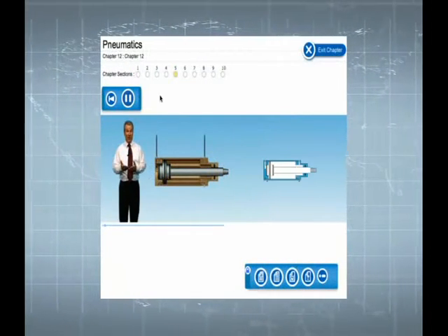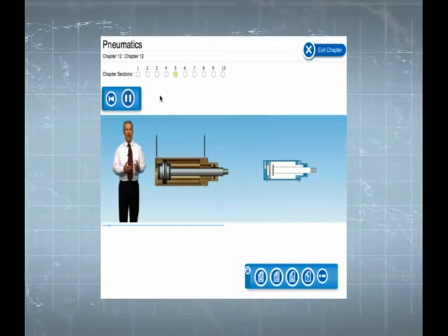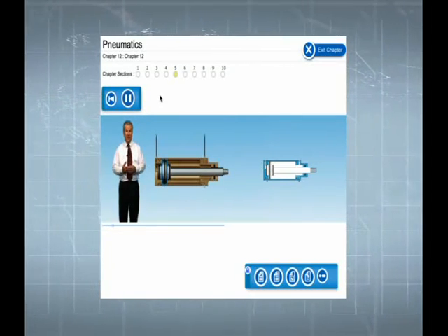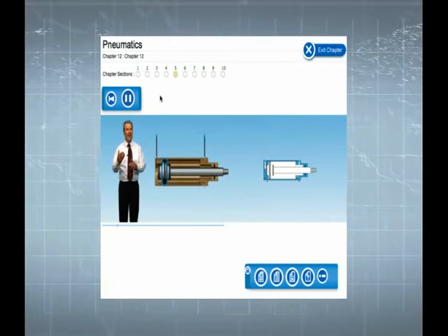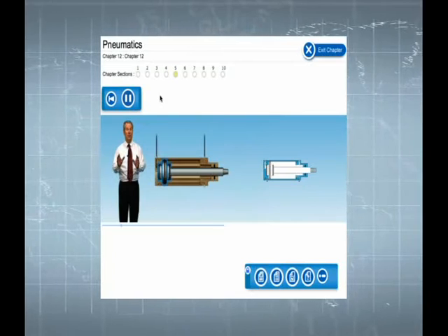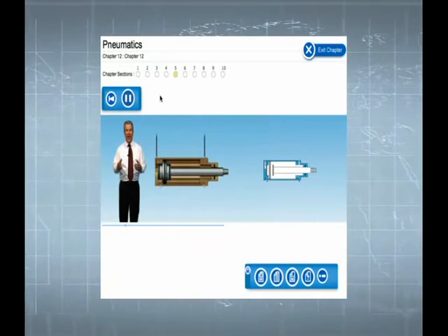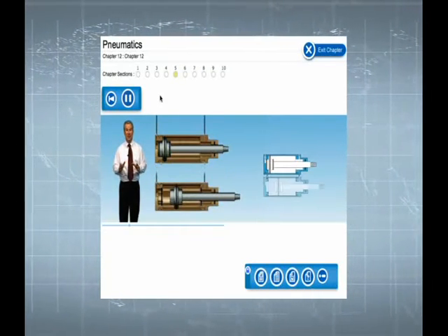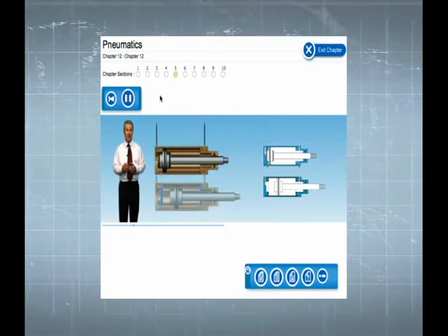Cushioning is achieved through the design of the piston. As can be seen, inside the cylinder there is a main piston to achieve the movement of the piston rod, and attached to either end of this piston is a smaller cushioning piston. The cushioning pistons have seals attached. Alternatively, the seals may be attached to the inside of the body of the cylinder.